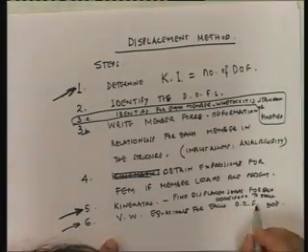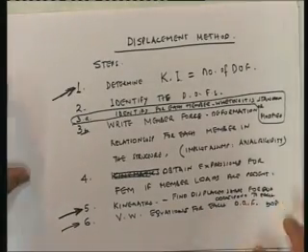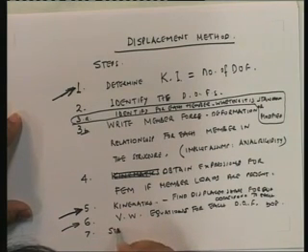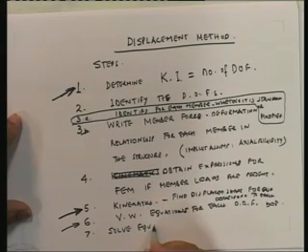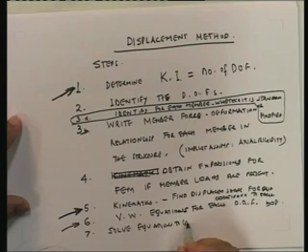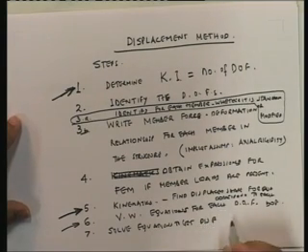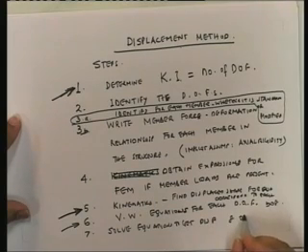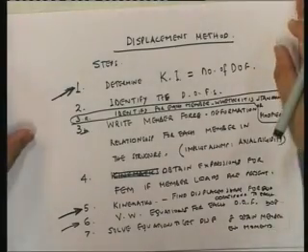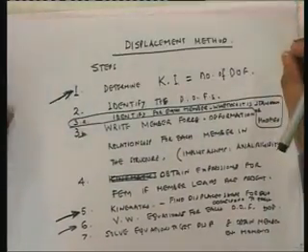There are some considerations that we will show you over and over again which go into this. Seventh, solve equations to get displacements. Eighth, obtain member end moments. And once you know member end moments, then you can get the rest. So this in essence is the displacement method.